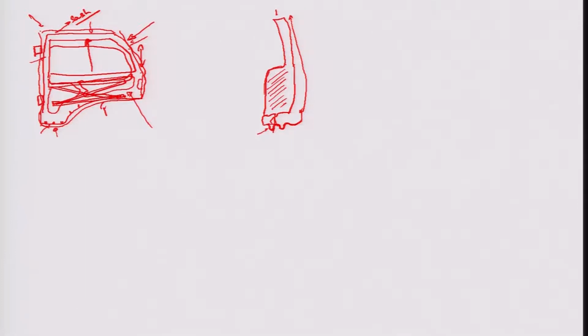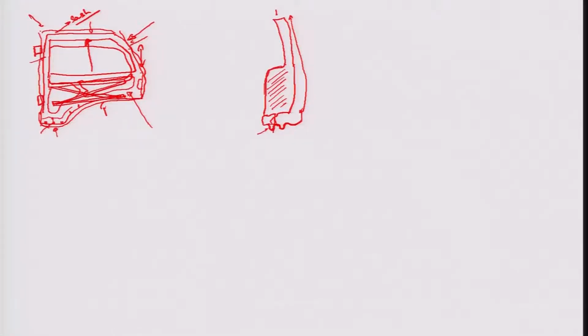So there is a point typically where there is not so much pressure because of some deterioration of the rubber part, okay, and the water may actually go inside the door and create water logging, and this water logging, if it continues after, let's say, a few thousand miles of driving, may create rust problems associated with a lot of bad appearance defects, particularly when the automotives are older, and it also tries to jeopardize the moving components within the door, which may be related to the hinges, or let's say related to the scissor lift which is used for the regulation of the window or movement of the window along the door sash, etc. of an automotive.